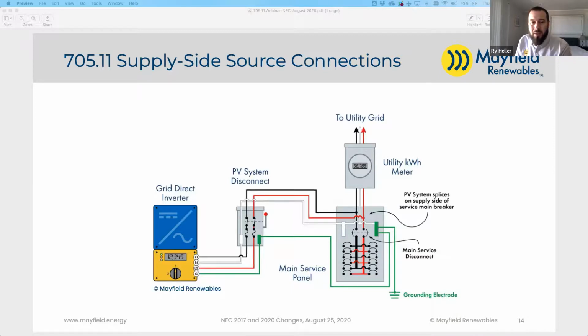And there's just the theory of having that single path to ground and not creating a parallel path. Then you get into, okay, now you bond both together. There have been exceptions in the past where you didn't have to bond them together, and that's a whole other argument to have. Obviously you have to take it up with your AHJ, but this method is the fastest way to go and the cleanest way to go.